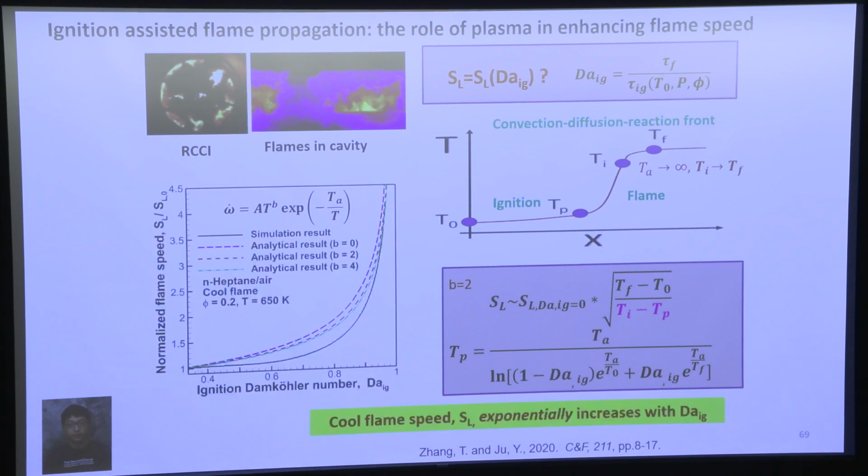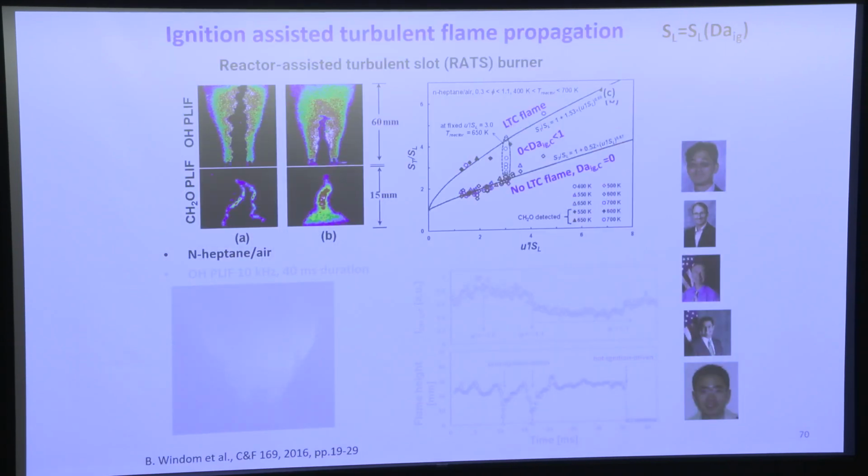So now, coming back to show again the theory: if you have a cavity and enhanced combustion, this plasma-assisted ignition, assisted flame propagation will help you stabilize the flame. And then the key question is, how do you generate a big volume of plasma? We just got a contract from the Navy to try to develop this kind of concept to enhance flame stabilization for UAVs. We'll see how it goes.